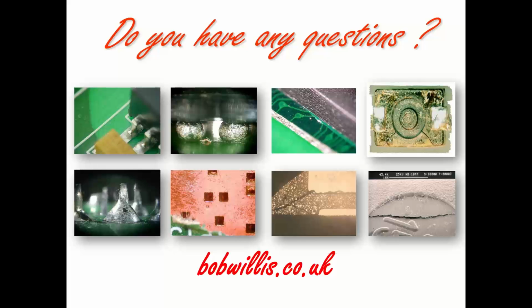But seriously, the point is that it's cost and return. Baking is a pain to do, first of all, because you can't bake a massive pile of boards in an oven, because the boards take a long time to absorb energy and get up to temperature. So actually getting the baking process done is quite difficult, time consuming and costly. But if you're looking at a failure rate in manufacture of, let's say, 2 or 3 boards a week, it really is nothing in terms of cost. So again, you've got to balance it.